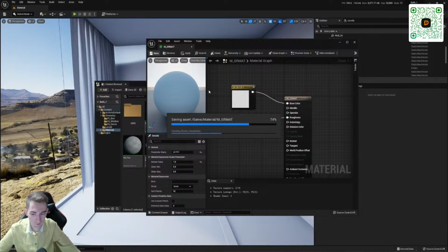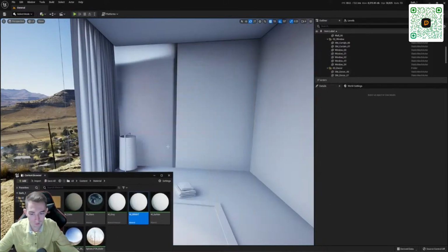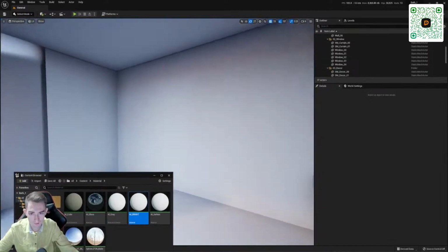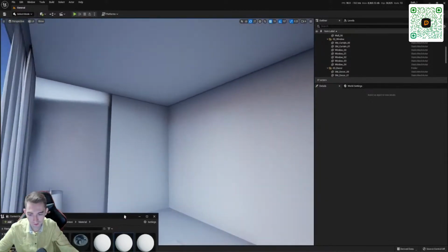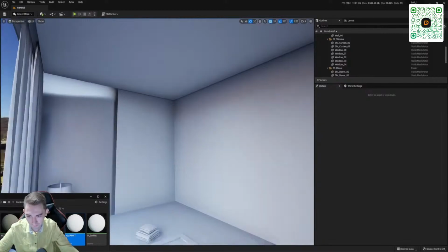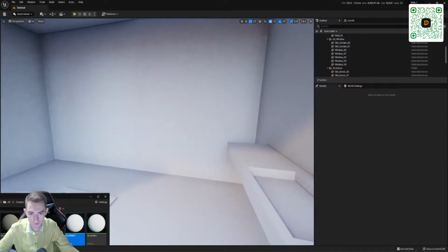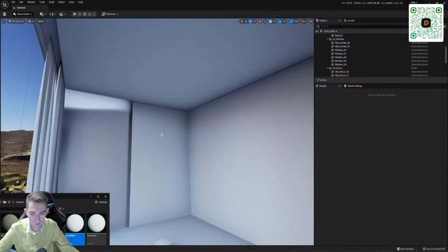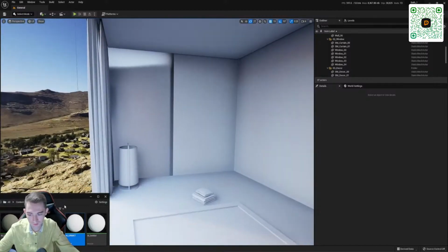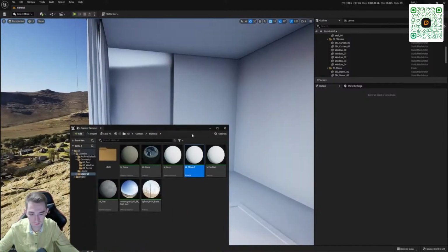This is how the Surmat material looks. It's just easier to adjust the light that way. In principle, it is the same technique as in 3D Max. That is, we assign a color. It is better, of course, to assign a color according to the interior. If it is a dark interior, then even more so it should go into a dark color. If it is light, then it is lighter.